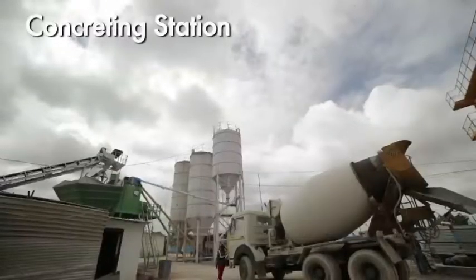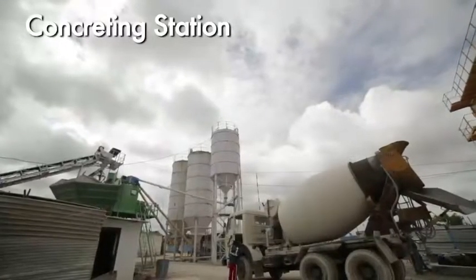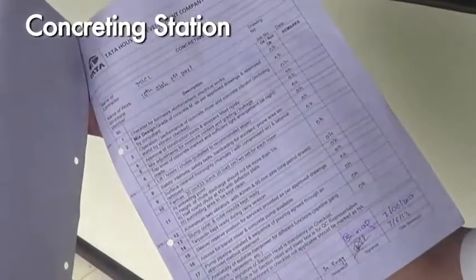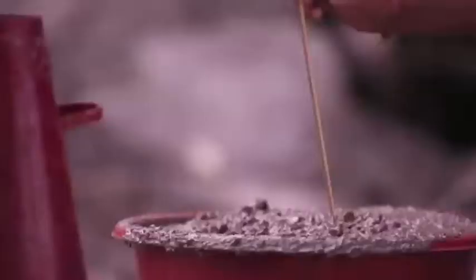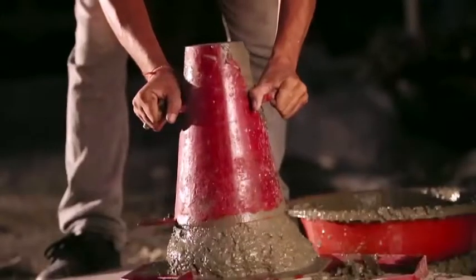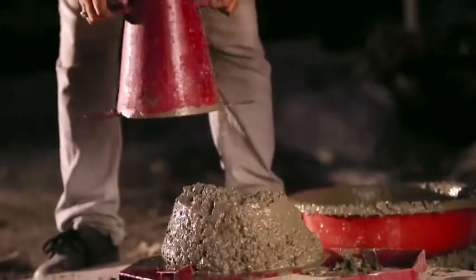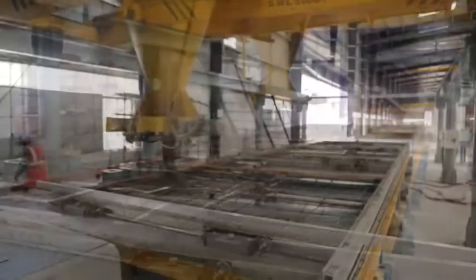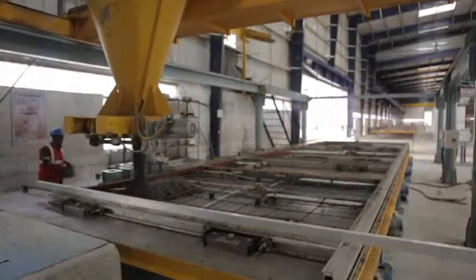Concreting station. Concrete produced in the batching plant is transported to the casting yard. Check the docket for confirmation of grade of concrete and batching time, and then check for slump. Check the condition of the pallet vibrator and sufficient manpower needed for concreting.